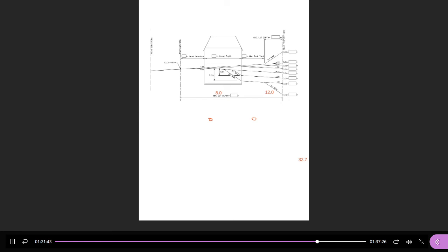Right? If I was between here and here, if I was in here, I would just come up at 3% to the building, and that would be it. I'd be done. And then if I wanted to design these 2 points, I could come down at 3% and up at 3 to 1. Right? If I came up between, I would come down at 3% and up at 3 to 1, and so on. So how to design those things, I'm going to show you.